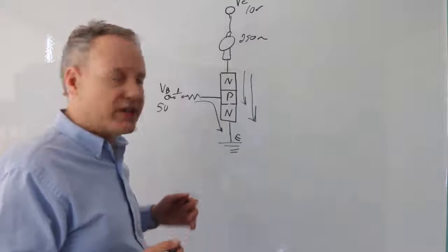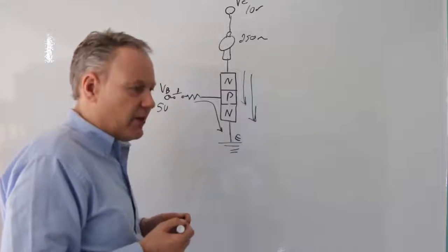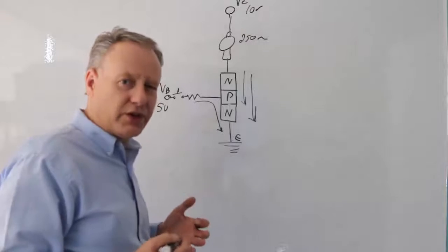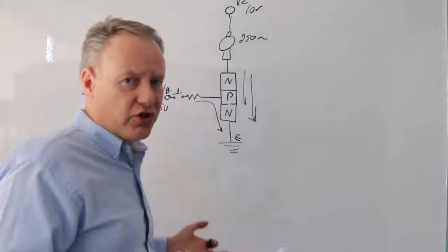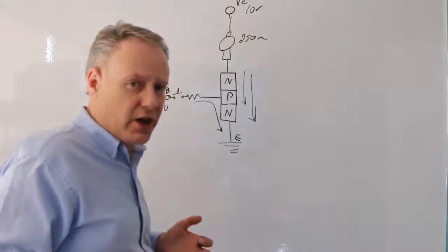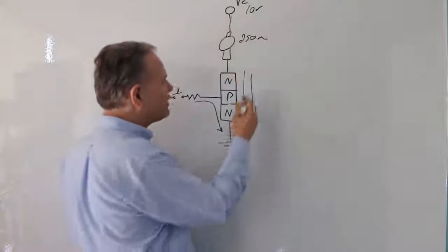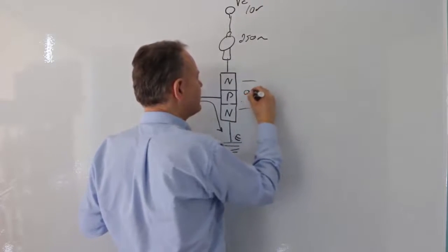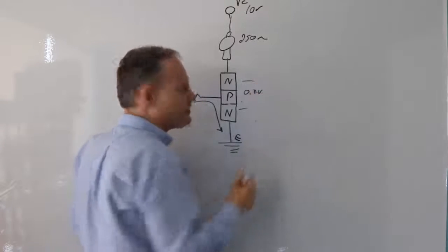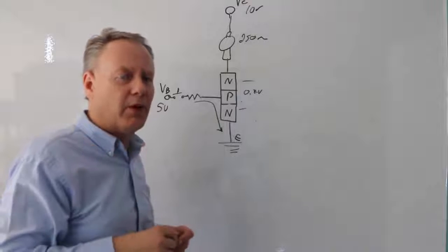First thing I want to do is study the current that's going through here and actually do the math and see the formulas, but I have to understand the voltages really to do that. And we know that Kirchhoff's law says that the voltage drops in series equal the source voltage. Well, there's a voltage drop here that we haven't talked about. It goes from here to here, and it's around 0.2 volts. It fluctuates to some degree, but it's pretty small, but we still have to take it into consideration.